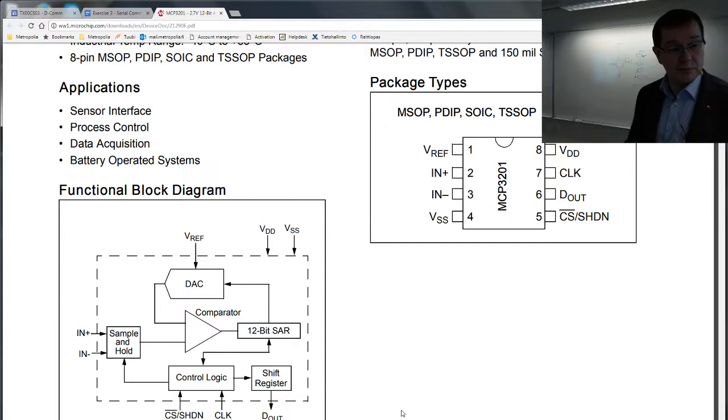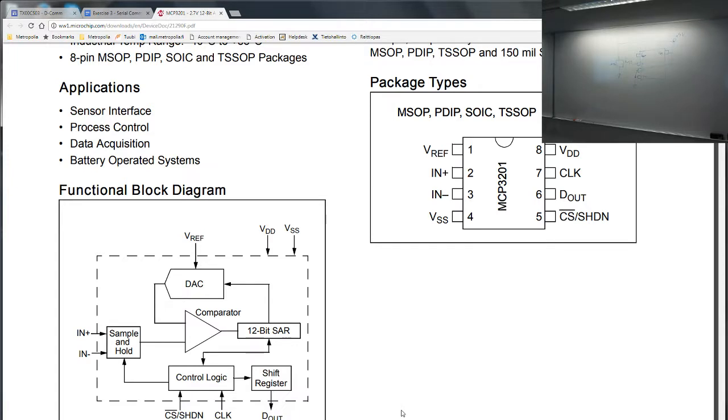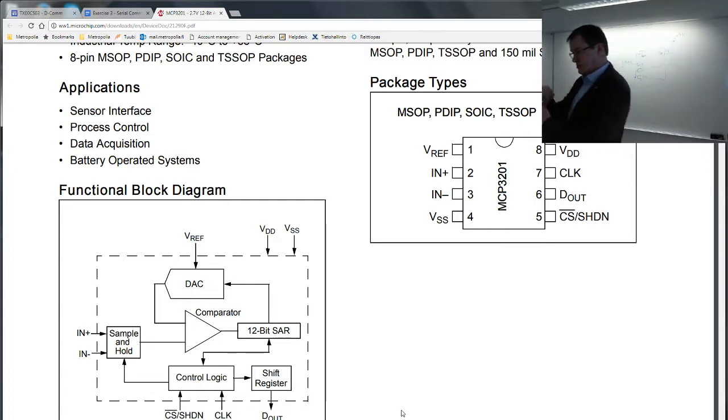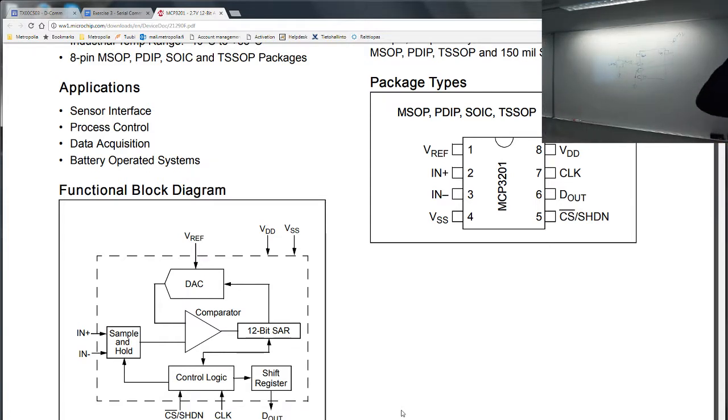And by the way, it's a good idea to stuff them on this conductive styrofoam on the evaluation kit. These are electrostatic sensitive devices, but well, I haven't destroyed any of these for 25 years or so. Basically, when you are handling this kind of electrostatic devices, you should not handle them too carefully. When you are too careful, you can zap the pins, but if you are just taking them from the several pins, if there is any charge, it goes like this, not through the chip.